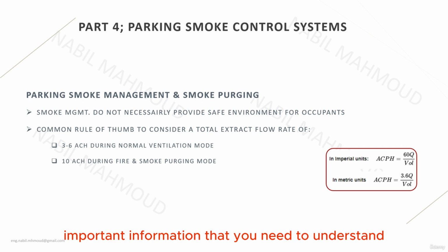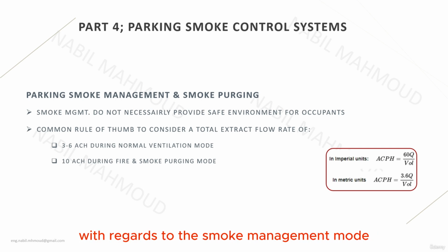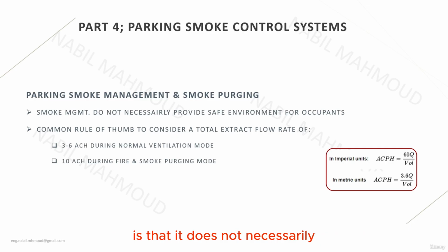However, the most important thing to understand with regards to the smoke management mode is that it does not necessarily maintain a safe environment for the entire fire duration. It is only required to maintain a safe environment until the occupants complete the evacuation from the place.